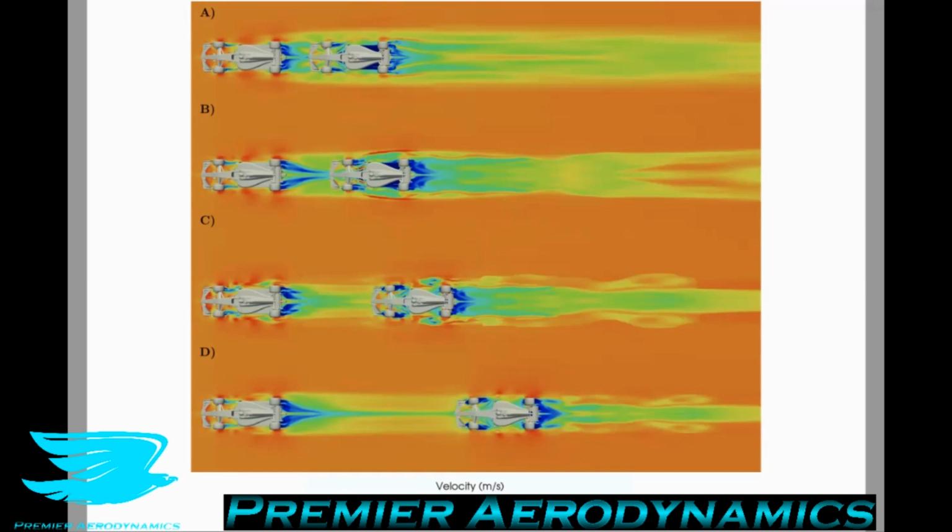So as for the lead car, this is interesting though. It can be noted that, so for the downstream car, it's severely affected, its wake is affected, all the components are affected, but for the leading car, its wake is not noticeably modified in terms of the shapes and contours by the presence of the following car. The aerodynamic coefficients that are evaluated for the leading car experience only a small variation of 3% or less, and that's even when the distance between the cars is 0.25 lengths downstream. Now that's a lot less than I expected it to be.